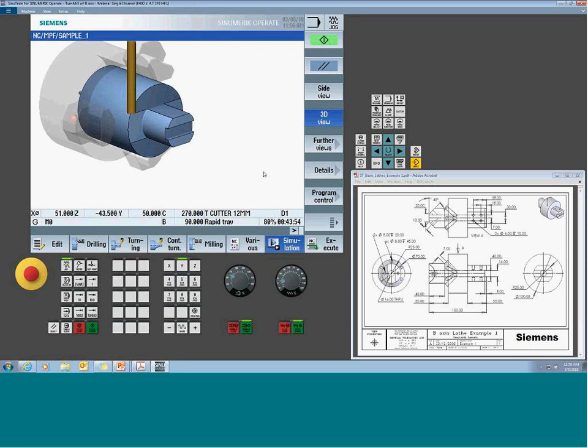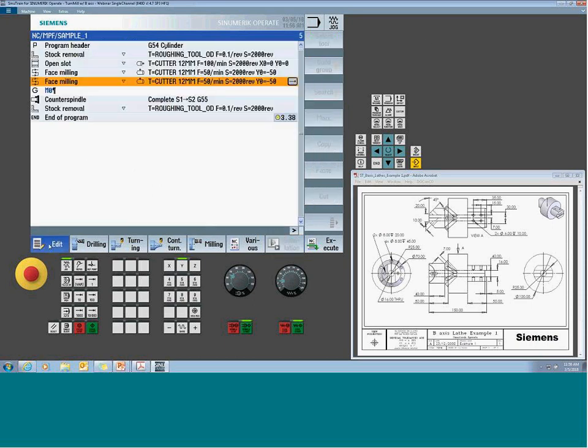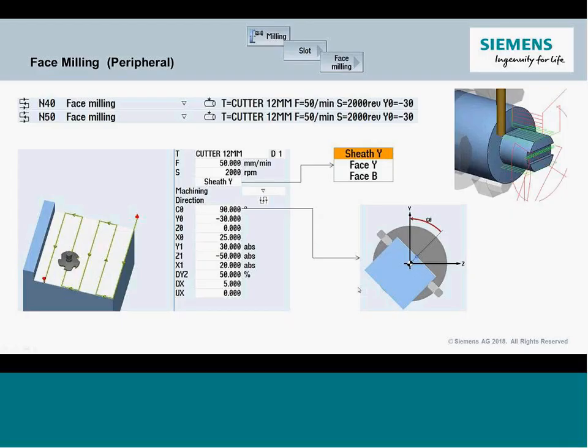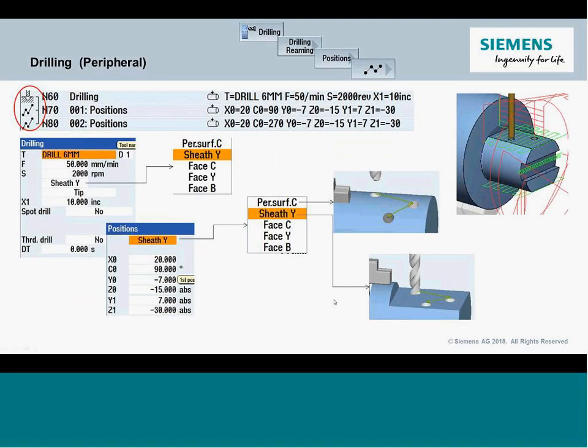Some people get confused where C0 is, so I even find myself just putting some geometry in to get my head around where this whole thing is falling. And then if I have to, I can index things 90 degrees from each other. Again, you would continue on with the transfer and the machining of the back side. So that's some flats there. Now I actually drill some holes.